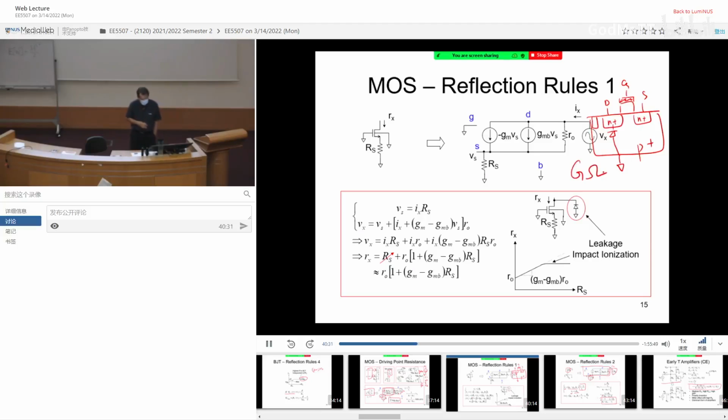You want to create such that the resistance is equivalent to gigaohm. So think, when I look into here, I want Rx to be approximately gigaohm. What does it mean? It means that if I apply 1 volt, it should only draw nanoampere. Am I right? Okay? Now, what if I'm not happy? I want it to be 10 gigaohm. It means if I apply 1 volt, it should only draw 100 picoampere.